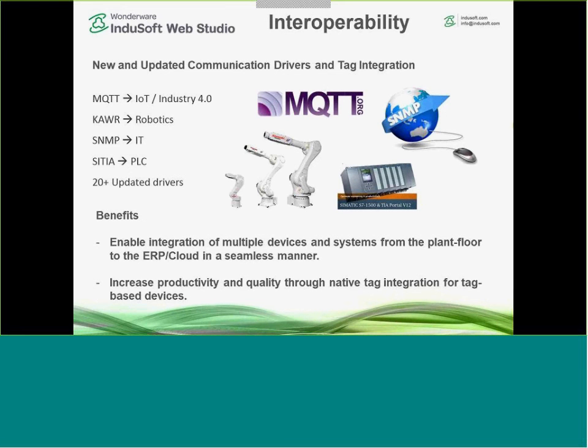The TIA driver has been released for a while, but we have made enhancements now available in Service Pack 1. It's not only a driver, but also an import wizard, which allows you to browse tags from the Siemens TIA project for the S7-1500 PLC, and also communicate with the Siemens S7-1500 using tags instead of memory addresses.